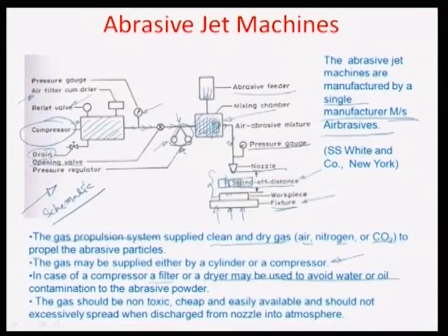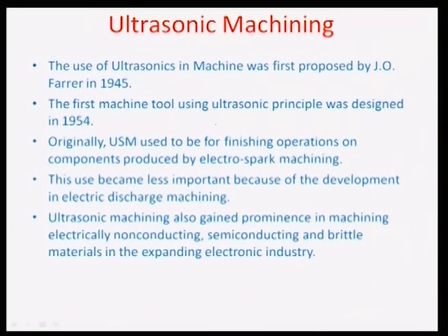So here the second part of the process, which is important for understanding some of the micro device fabrication that will come later, is the USM or ultrasonic machining. Ultrasonic machining was developed in about 1945 or so by J.O. Farrer, and the principle in this particular machining is very simple: instead of having a direct impact of the grains, as typically happens